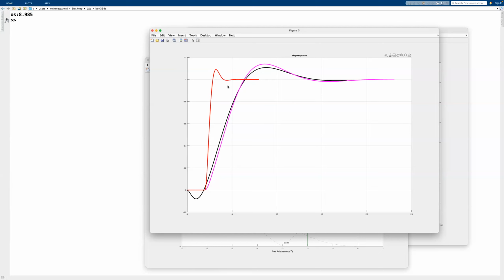Of course, they will never match each other. The Smith predictor version would be quite a bit more powerful and more optimizable in that case, because we are not dealing with the approximation poles and zeros. We're just dealing with the delay part with a structure, and we're extracting the non-delay part, and we're focusing on that. So it is less restricted in that case.